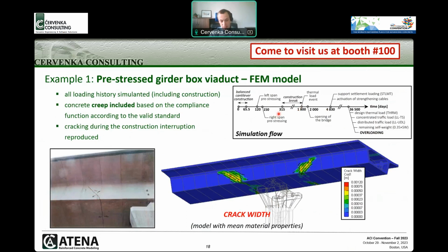So we ran the simulation in a kind of complex way, where we also included the construction period and simulated the balanced cantilever construction method, then pre-stressing of the left span to the right span to create a continuous beam, and then when the bridge was still unfinished, we prescribed the thermal loads according to the on-site measurements.